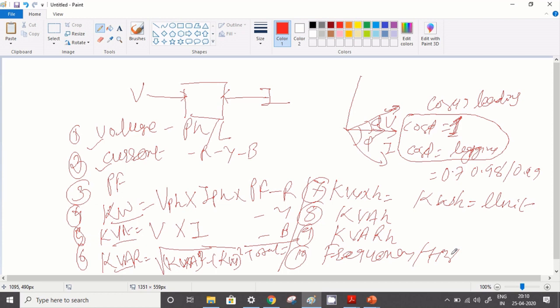So with this V and I, you can easily calculate all these 10 parameters which your meter will be showing in the display. And based on your technology, all these parameters will be available on the remote monitoring system. So this is the basic meter which requires a voltage and current signal. If these two signals are connected properly, and if the ratio and parameters are configured properly inside this meter, then all your parameters will be correct. Any changes in the meter values, the ratio and configuration will disturb all these parameters. So you should carefully enter and configure your meter in the energy management system.